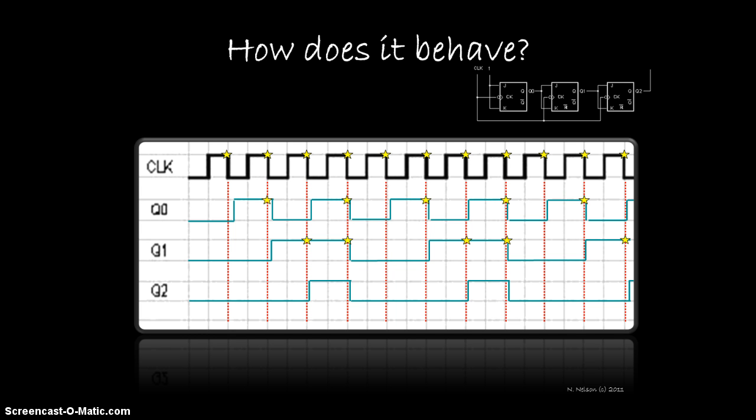Reading the waveforms, you can see that during clock cycle 1, the output is 0, 0, 0. During clock cycle 2, it's 0, 0, 1, followed by 0, 1, 0, 1, 1, 1, and then back to 0, 0, 0. This pattern then gets repeated. That means that only 4 of the 8 possible transitions are shown. It's important to understand exactly how the system behaves, so you need to use a tool, such as a state transition table, to identify exactly how the system behaves under any condition.